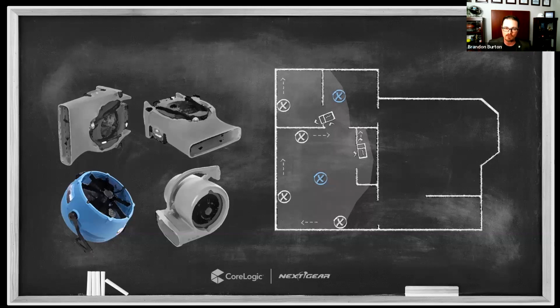If you find areas within that affected space where the floor is substantially wetter or cooler than the air at chest height, your air movement installation is not doing the job. Right? Either an additional air mover is needed, or some adjustment on angle of air movers is needed. Continue to adjust until you get an equal condition at both of those levels. Now, taking 100 hygrometer measurements is not practical. And that may be the first thing that popped into anybody's mind who's used a hygrometer as soon as I said that. So taking lots and lots of hygrometer readings is not going to be practical.